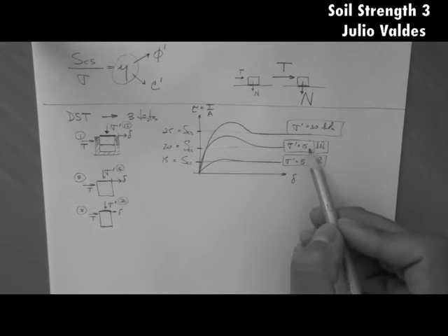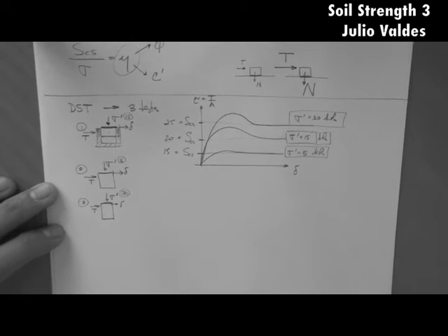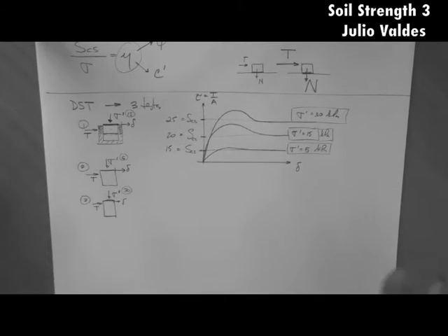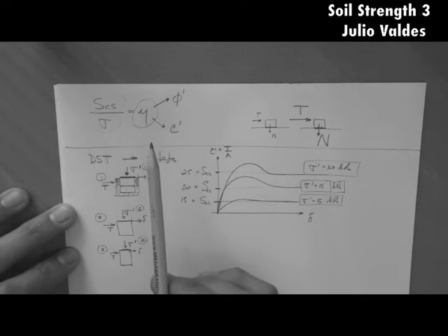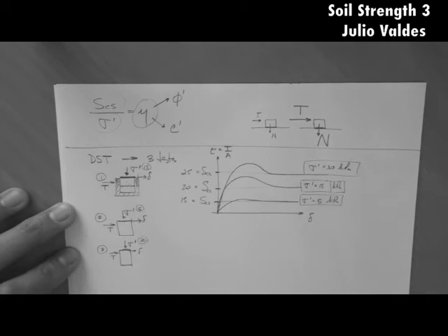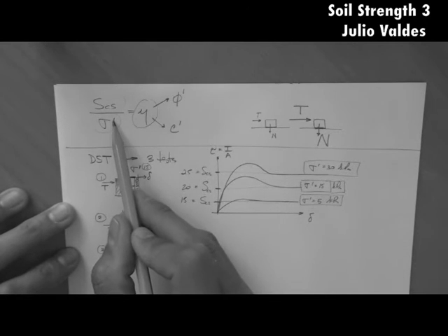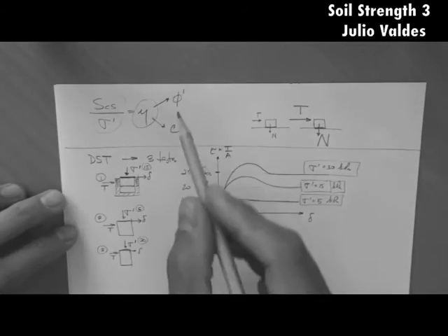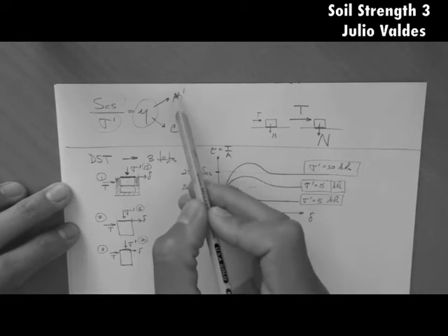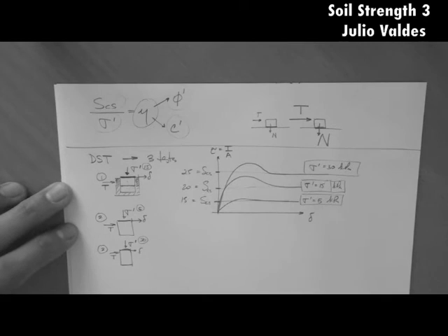For different imposed stresses. Now, that is the first part of the procedure to determine the relationship. Remember the relationship between the strength and the stress imposed, which in this case we could put a prime here, right? Because we're talking about effective stress, stress that the particles feel, not the water. And that relationship is described by these two parameters, which we haven't figured out yet.